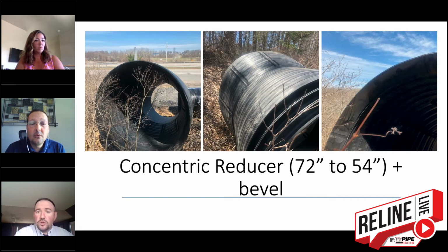Just more examples. Once again, you can see what they do is they take the circular pipe, cut little sections out of it, then fold the remaining sections in and weld the pipe back together. So what you end up with is a nice taper or a nice conical section that allows the reducer to be created. And it's hard to tell, but if you look at the picture on the right, we've plated the pipe up so it's a nice flush finish instead of the pipe ends being all exposed in open profile. So it's completely solid and built so it'll last for decades.